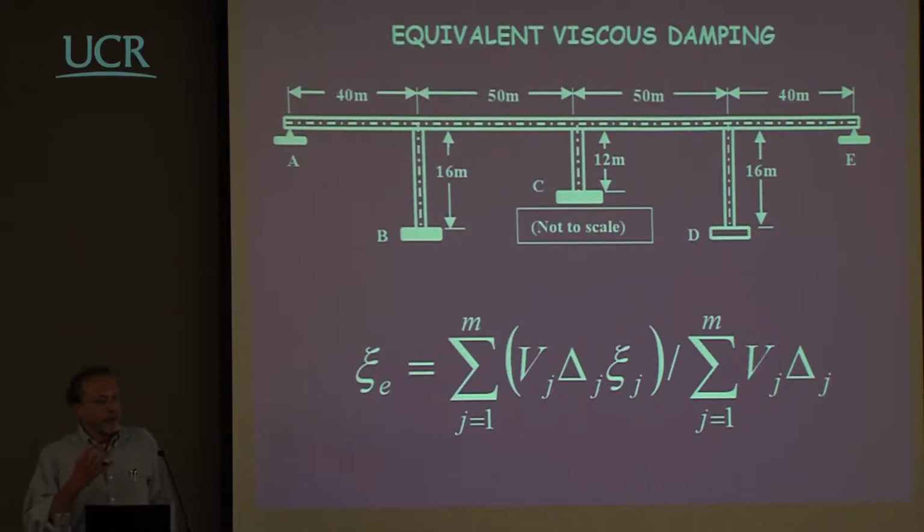This is important because now I will go to isolation, but isolation means to have some element where you have some concentrated displacement and you have some well-defined damping, because the damping is something which is connected to the nature, to the essence of that element. If you add an isolator on top of a pier, and the pier is flexible, therefore the total displacement is going more to the pier than to the isolator, then the damping associated to the isolator has little effect on the global response of the structure.